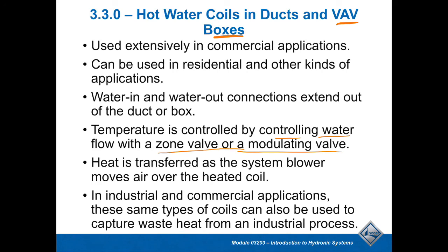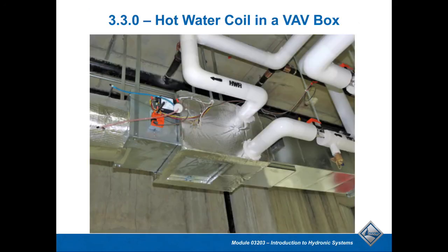Certainly the interior as well. And obviously the valves, you're going to have control valves that have to control how much water goes into those applications. And most of the time you would have some sort of modulation, but it doesn't have to be that way. Again, just a basic fan coil.